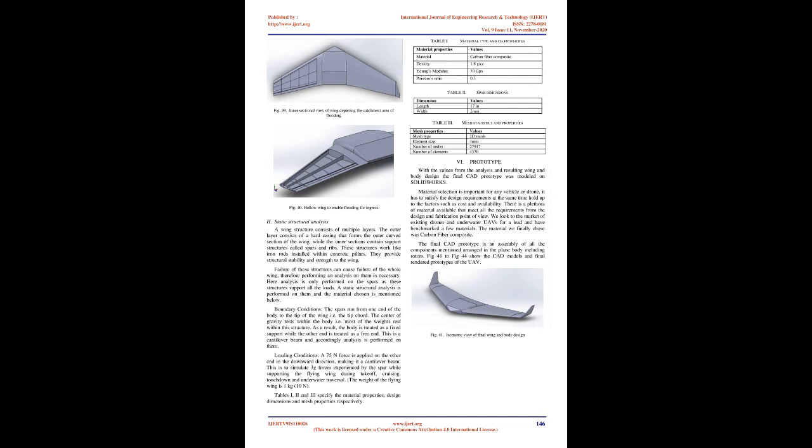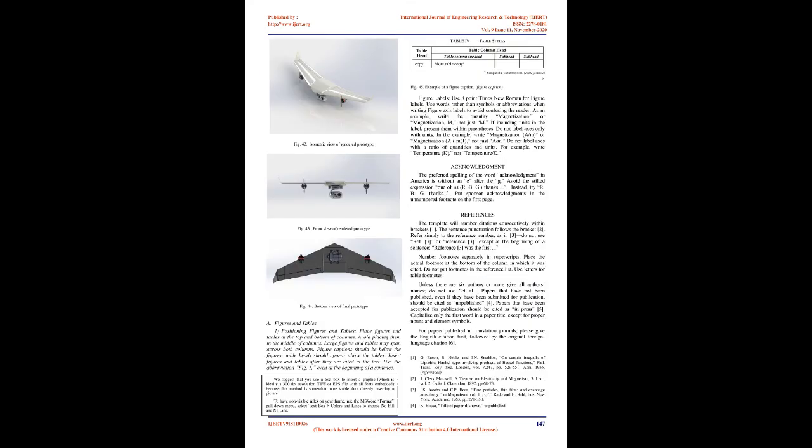3. Center of gravity. To determine the center of gravity we first determine the neutral point, NP. The NP is a point on the plane where the moment is independent of lift. The center of gravity is then determined to be within 15% to 25% of the specified neutral point. The neutral point is determined by alternating the center of gravity until the curve is approximately horizontal to the x-axis. Later the masses are accordingly positioned on the plane body to gain the center of gravity at the determined point. This weight positioning interface is shown in Fig 37, while Fig 38 shows a three-dimensional view of the weight distribution.